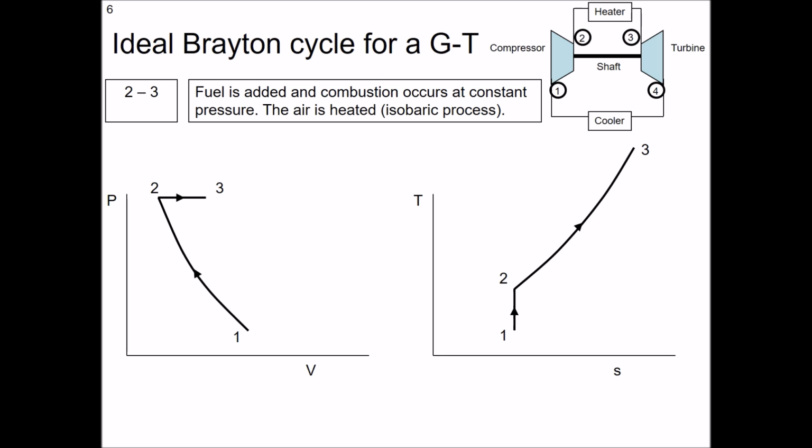So we see a huge increase in the entropy as that happens, and that's how the universe works. As we change chemical bonds into energy, the entropy will increase because the value of the energy is starting to degrade. But that's exactly what we want to do. We're handing energy down from a chemical potential energy into becoming thermal energy, which is what we wanted to do. So we see that increase on the TS diagram.